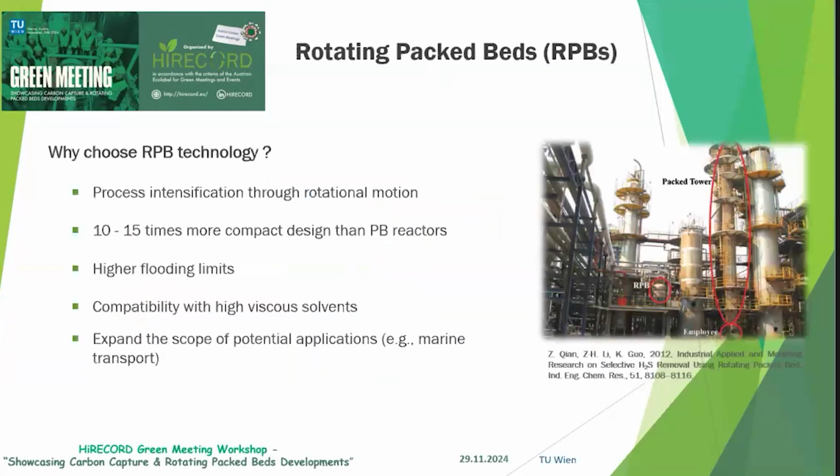We have already explained why RPB technology is necessary for this kind of application. To summarize, it's a process intensification device which results in a 10 to 15 times more compact design, as you can see in this figure. It also has higher flooding limits, and you can use more viscous solvents. And also, it can expand the scope of potential applications, maybe to marine transport and more.